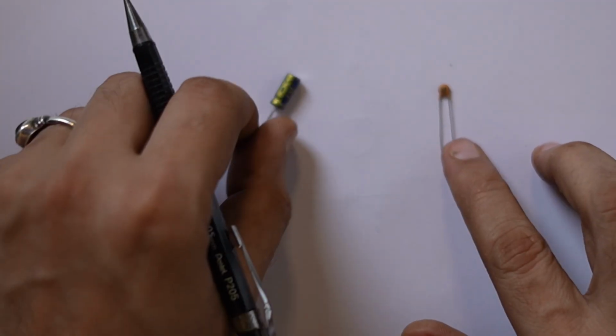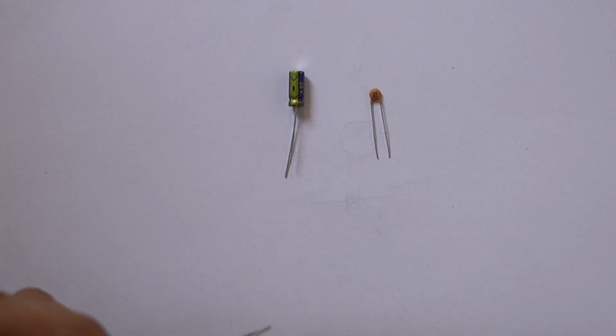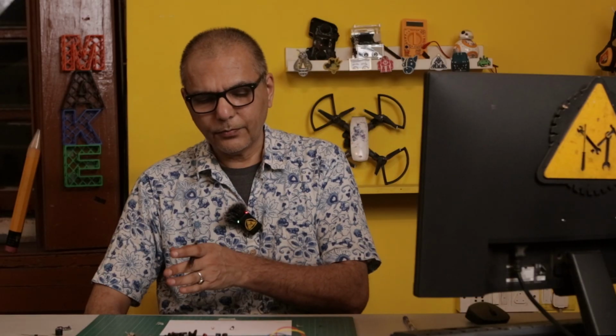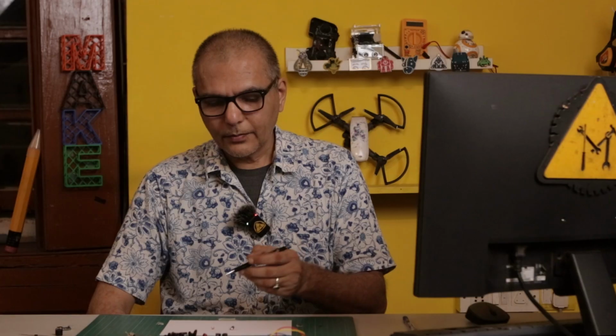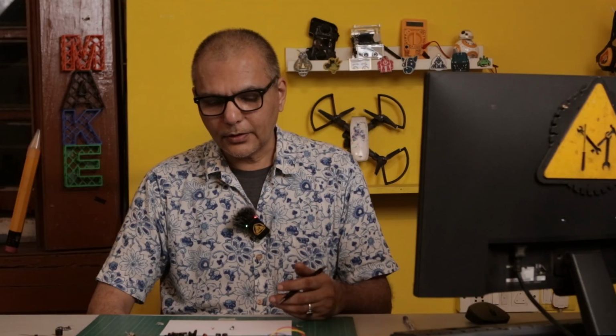So if you look at these two devices that you see right here, this one is known as a disc ceramic capacitor or just a disc capacitor, and these come in usually lower values, and their purpose is not so much storing charge as to filter out and eliminate noise or signals, or to act as an element in a filter. For example, if you are having a low pass or a high pass filter, then these kind of low value disc capacitors are used. And there is a big range of capacitors. I am not going to walk you through all, but just show you two of the very typical ones. So these are used mainly for filtering, noise reduction.